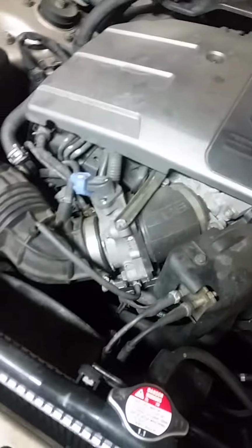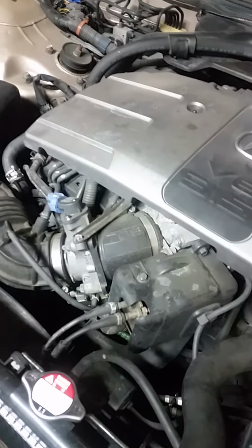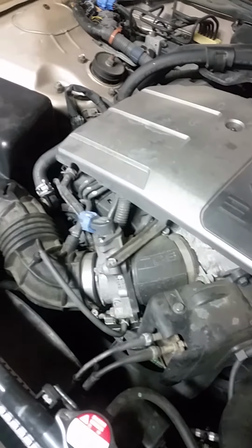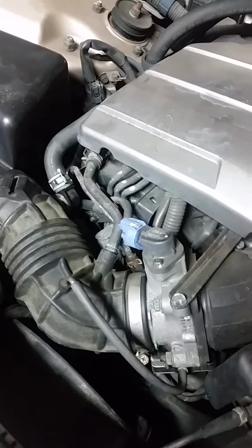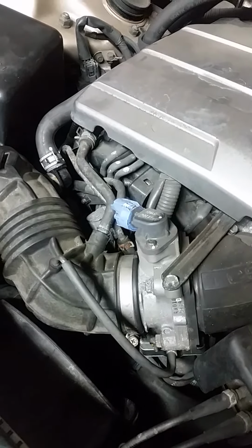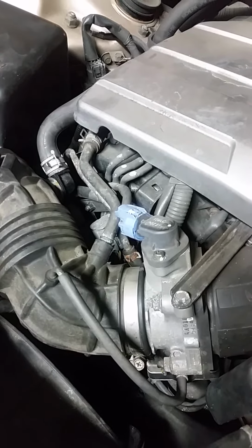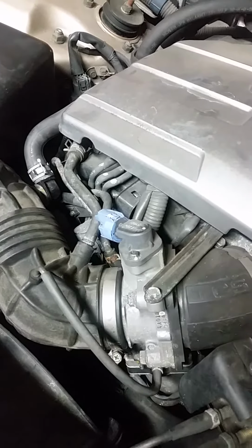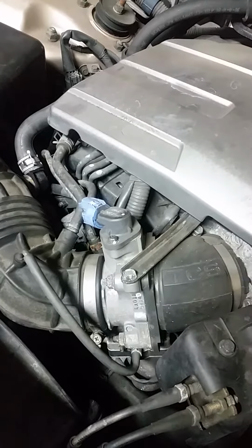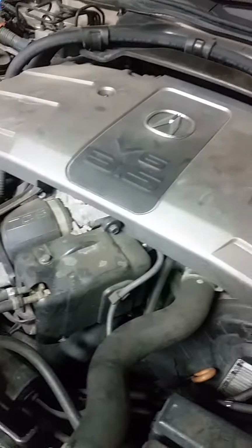This car does have an antiquated traction control system where the airflow is restricted to limit engine power by a second butterfly valve here. That's your throttle one over there. The second one, depending on whether the traction control system detects loss of traction, will close the airflow, reducing power.